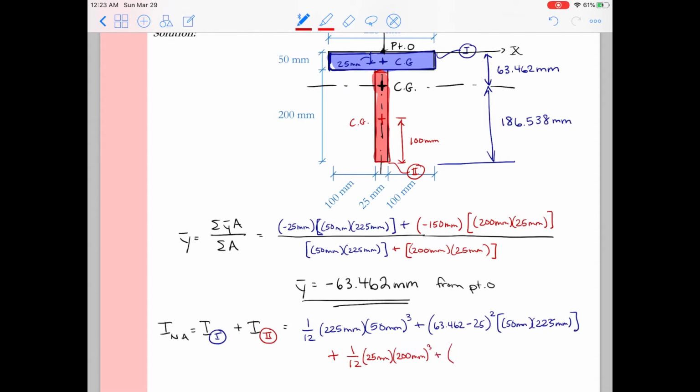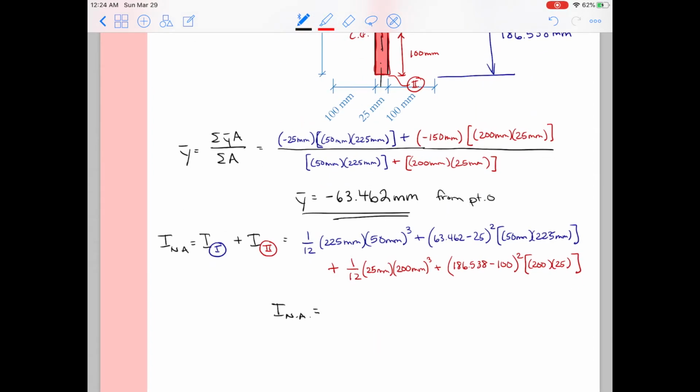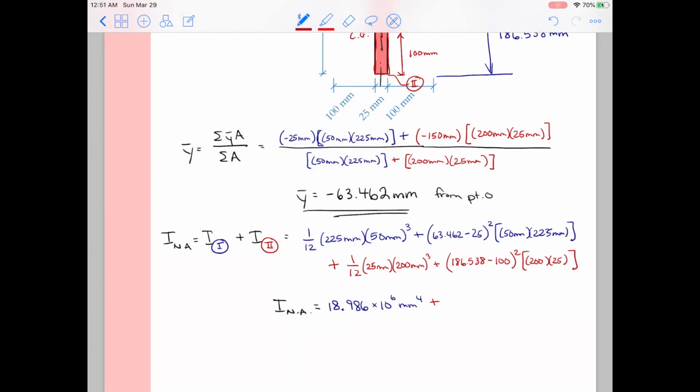So now using these values for y bar and the distances y top and y bottom, as well as the moment of inertia, now you have y and you have I. You also have M from your moment diagram, and you also were given the maximum allowable tension and compression stresses. So you pretty much have everything you need to solve for omega. So if you were a little bit confused earlier, now that we have these numbers, go ahead and pause the video one more final time and try to solve for the maximum allowable omega for both tension and compression cases.